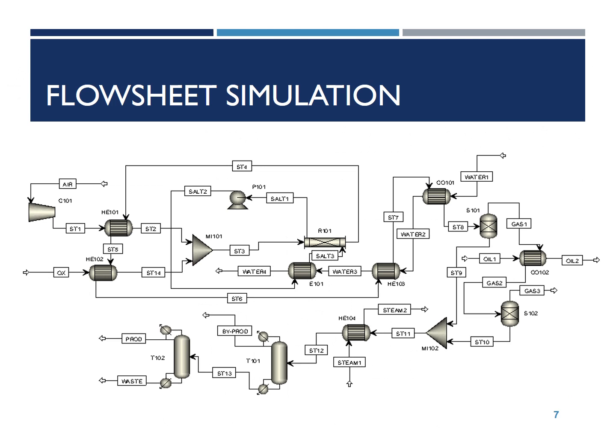As mentioned earlier, ASPEN Plus is developed based on a flowsheet simulation. This means that the simulation of an entire chemical process, starting from the raw material to the final finished product, is symbolically represented by different icons, where each icon stands for a unit operation, chemical process, input and output material stream, and input and output energy stream. In terms of ASPEN Plus flowsheet notation, there will be a block icon and a stream icon.